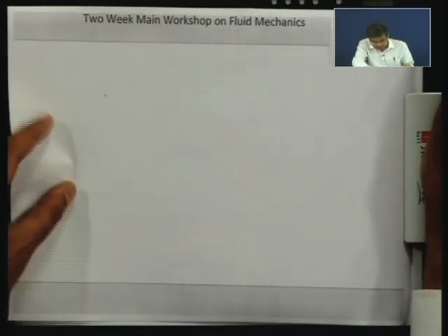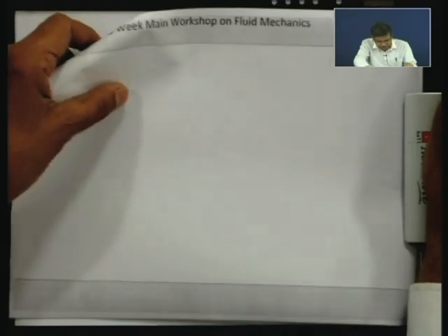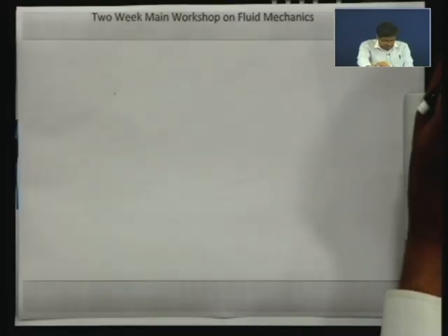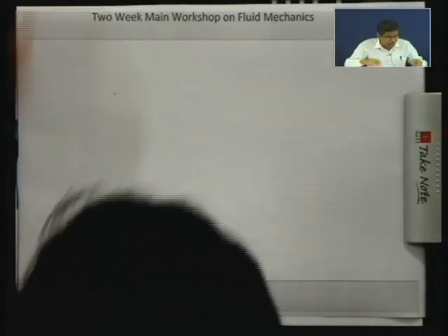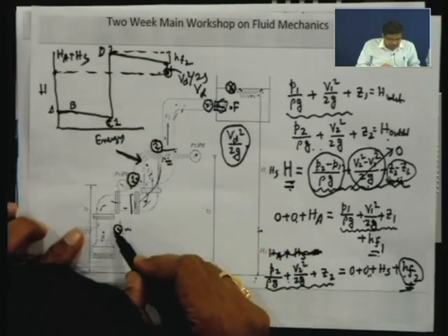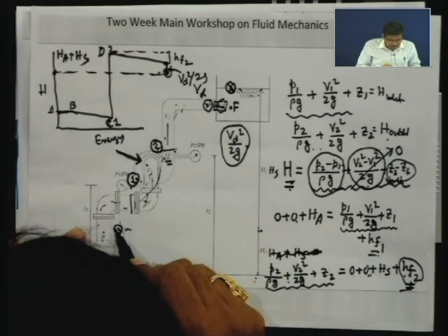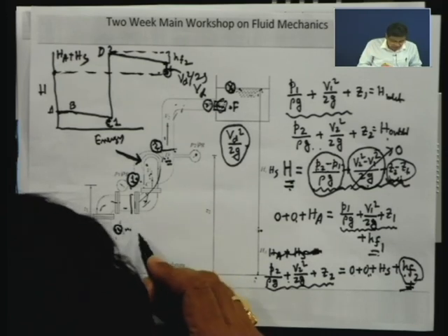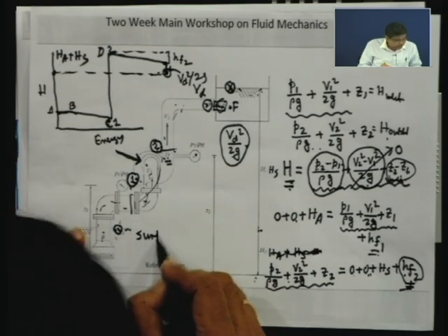a very important thing, that is the net positive suction head of a pump. Now, you see in a pump the most vital point is the inlet to the pump, because here the pressure falls, obviously because it is coming from the sump, that is, this is known as the sump, the level here.